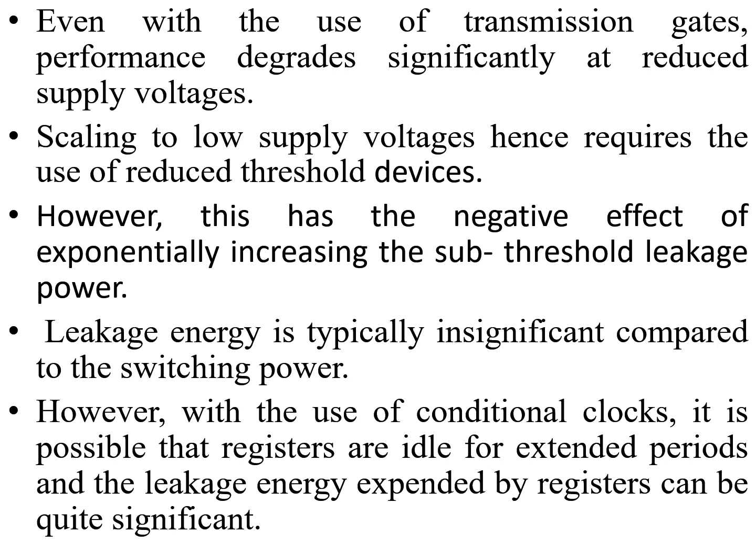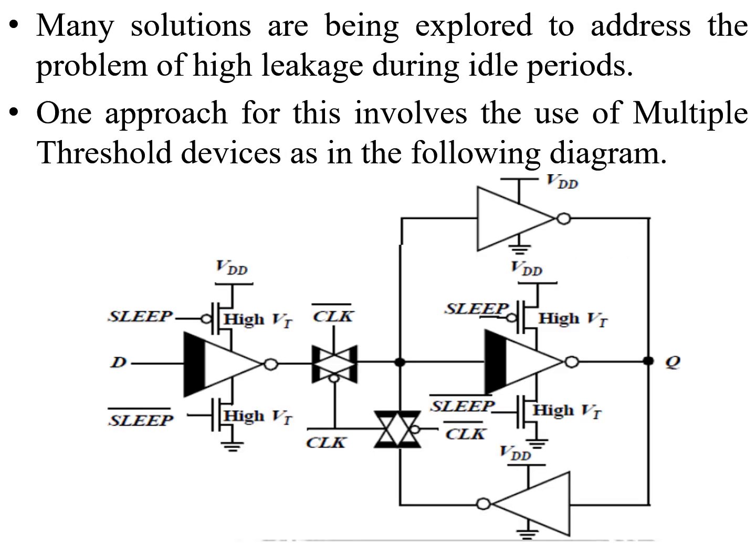However, with the use of conditional clocks, it is possible that registers are idle for extended periods and the leakage energy expended by the registers can be quite significant. Many solutions are being explored to address the issue of high leakage during idle periods. One approach for this is the use of multiple threshold devices as in the given diagram.